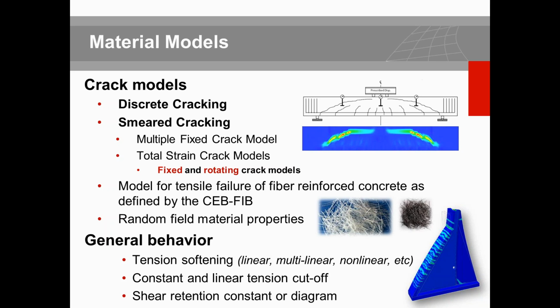and mimic this effect. However, in most of the cases, we are dealing with the continuum model, and in the continuum model, we don't know, based on the increment of the load or variation of the loads, how these cracks are initiating, how they are propagating, and how these could end to the final failure of the structure. For that concept, we have a smeared crack model with different formulations, multiple fixed or total strain. And also we are dealing with the fiber material models.